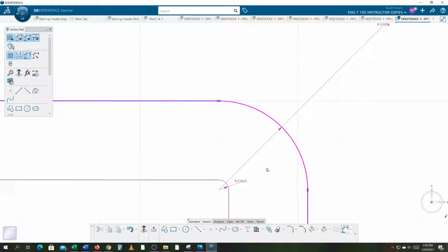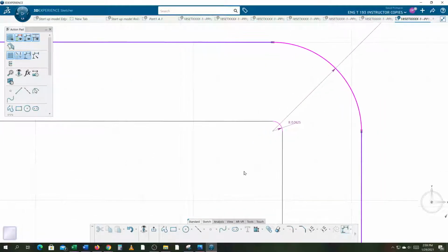So as a designer, hey, why can't we have a 9/16 radius? What's the big deal? The shop likes to try and grab as big a cutter as they can to try and hog out as much material as they can as fast as they can. So think of it like this: when you go to pick up tools and you want to buy a socket set or a wrench set or drill bits, they come in fractions, right? Because we work in America, we work to imperial standards.